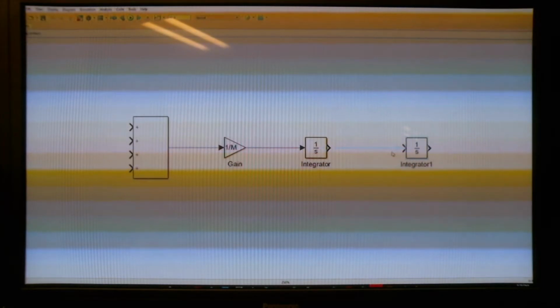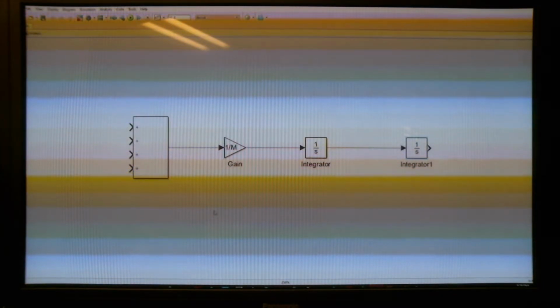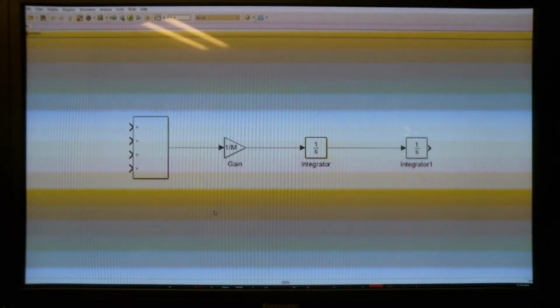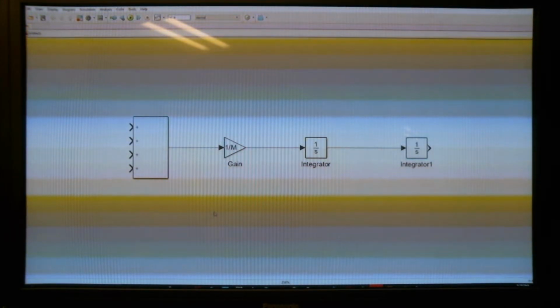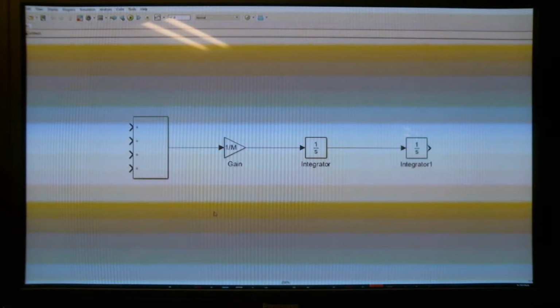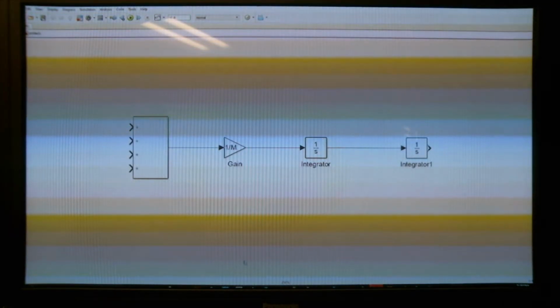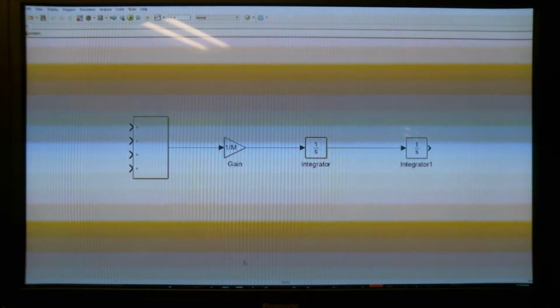So there's a trade-off with doing it this way. When you have a second-order integration being done numerically using 2 first-order integrator blocks, you will have accumulated error. A good example of this is if you're trying to model a bouncing ball.